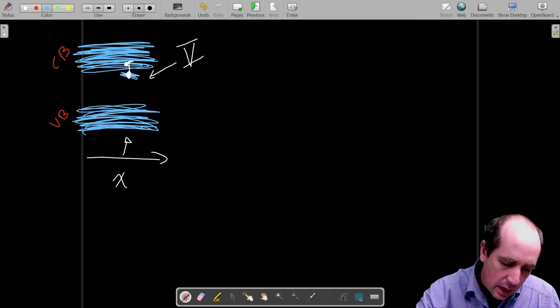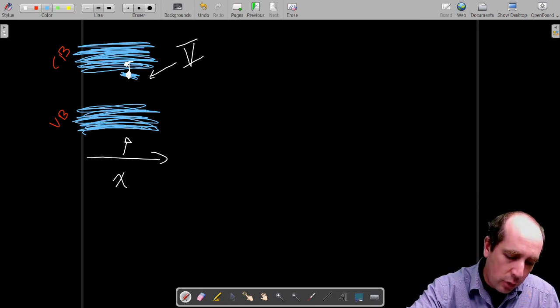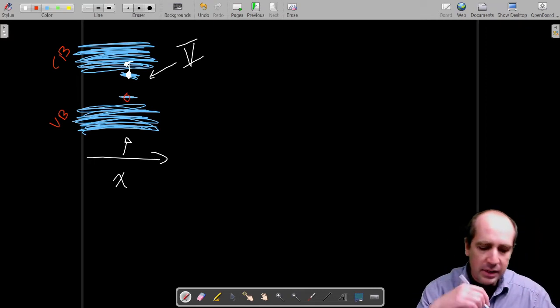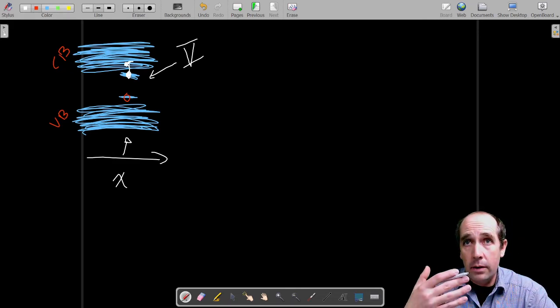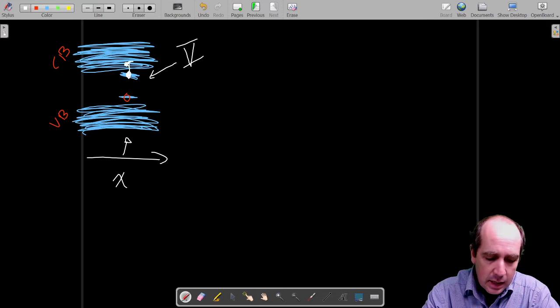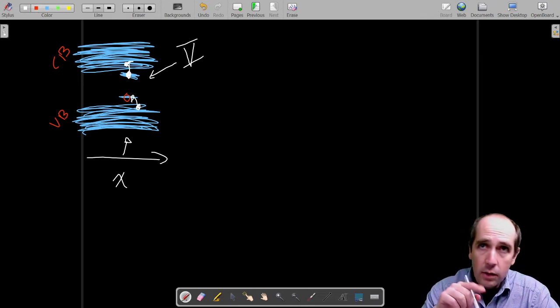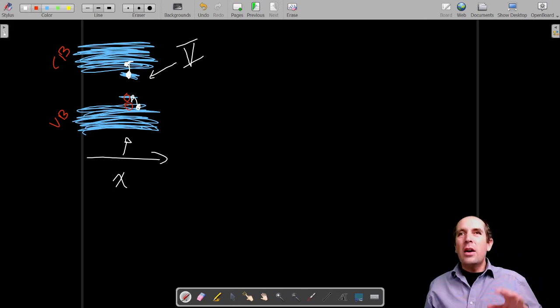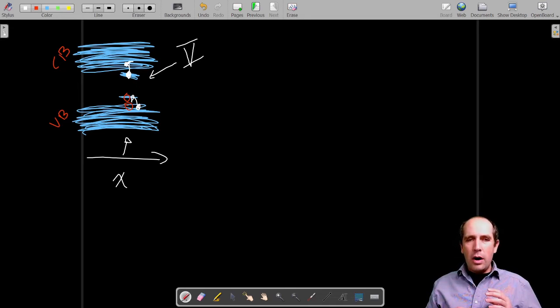They usually group 3 dopants. So in that case, what happens is it usually provides an empty level. So I will put this empty level very close to the edge of the valence band. And what will happen is that in that case, again, thermal excitation will be enough to populate this level. So electrons that were somewhere around here will quickly fill the hole and leave a hole behind in the valence band. And so all I said is at least intuitively correct at room temperature.